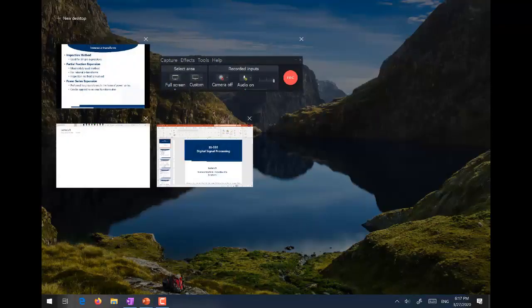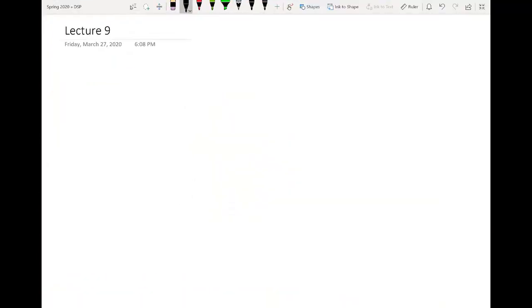As an example, let me show you a very simple case. If we are given a simple Z transform, how can we take inverse Z transform by using inspection method? As an example, let us consider we have a Z transform given by X of z is equal to 1 over 1 minus 2 z inverse. And remember, whenever we are giving Z transform, its ROC must be given along with the Z transform expression. So here let's say the ROC is magnitude of z greater than 2.